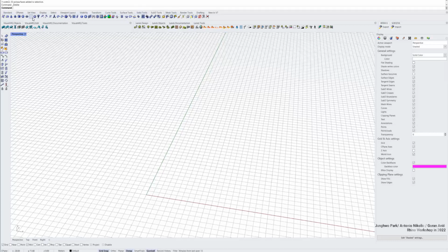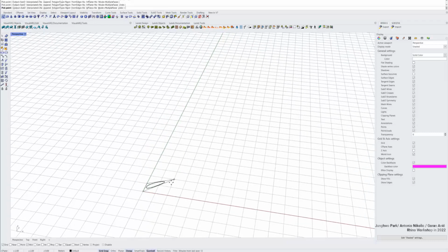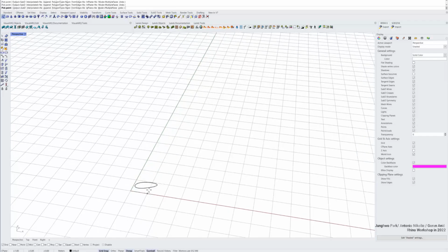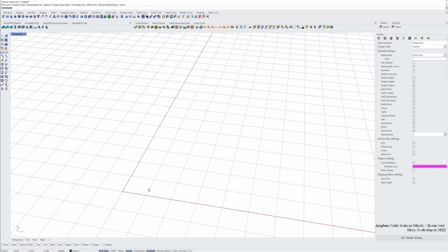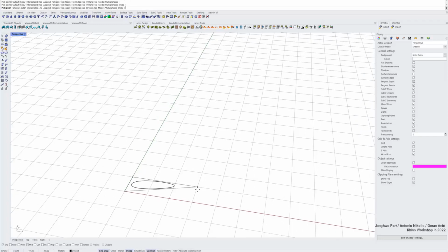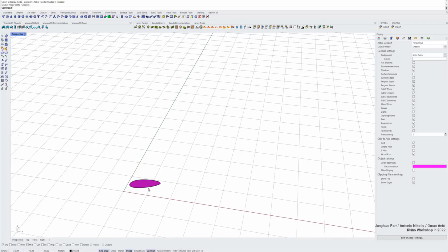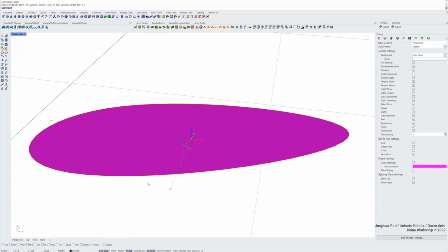Okay. So sub-D is a very interesting object. So let's have a look. You can create a single face, a sub-D face, by inserting 3 or 4 points. If you insert 3 points and then hit enter, then that's the sub-D face. Let me try again.